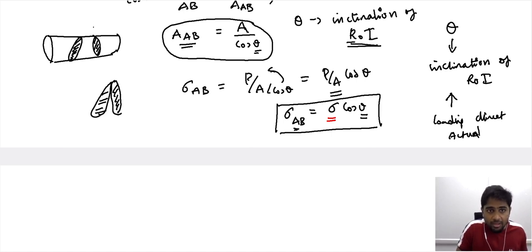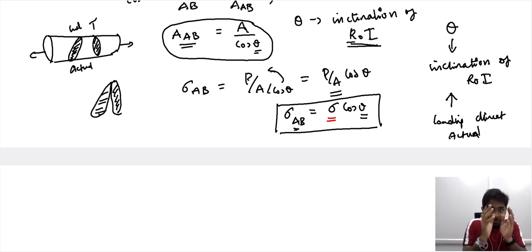So you have a test one and an inclined one, the actual one. Now the resistance offered by the actual, inclined cross-sectional area for uniaxial tensile loading is just a portion of the resistance offered by the cross-section area that is perpendicular to the loading direction, the cross-section area that we consider in the test condition.